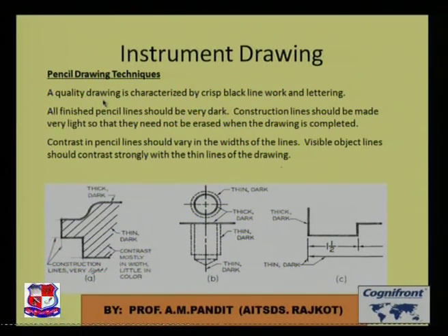What are the pencil drawing techniques? A quality drawing is characterized by crisp black line work and lettering. All finished pencil lines should be dark. All the outlines, as you can see, should be thick and dark, and everything else should be thin but dark as well. But we do not need to erase any unavoidable lines.